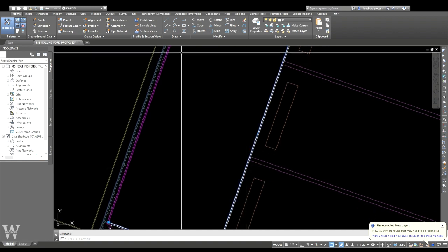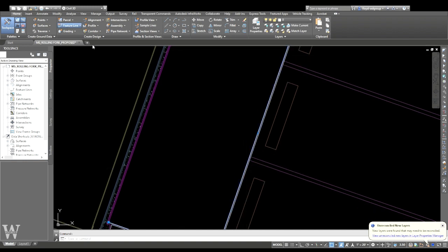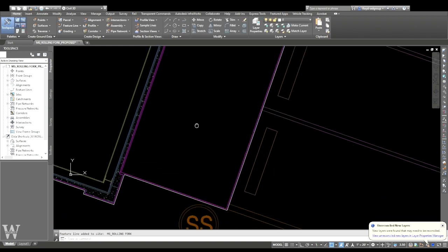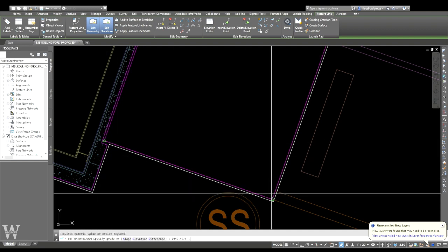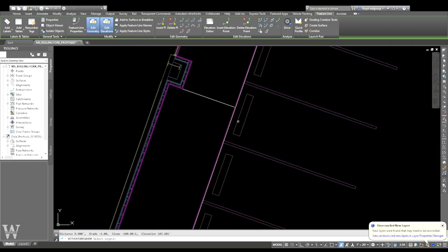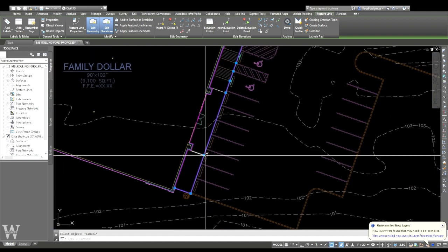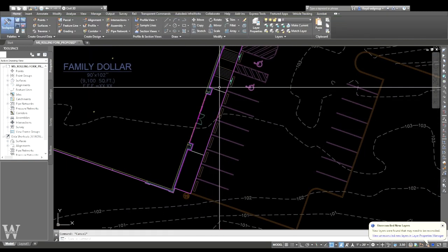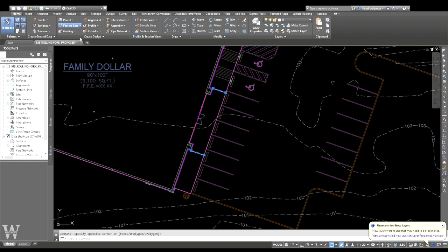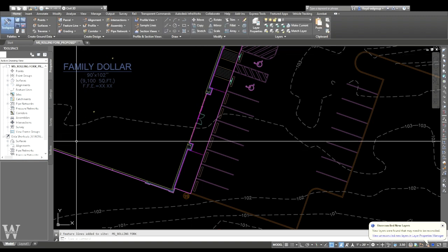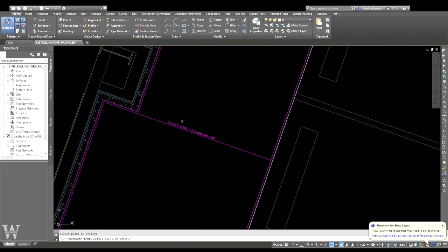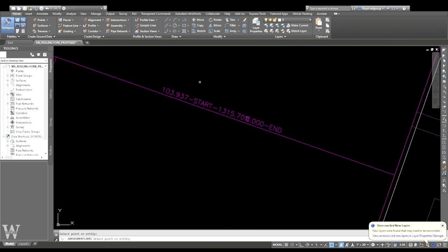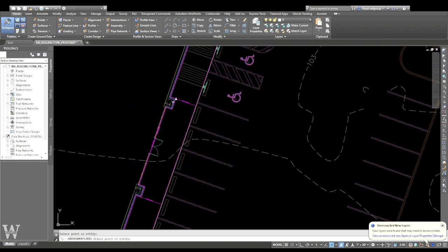So we click on here and feature line from objects. Okay. Go here. We're going 1% from here. Grade minus 1.0. And then we don't know what that elevation is yet, but if we take these two lines right here, create objects, and then we come back in here and label them, what we know is, we know that one end is 103.97, 103.97, because they should be the same if we did them right, if we went 1% and 0%.